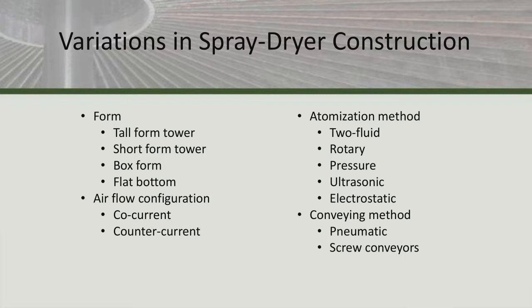There's various methods of atomizing the liquid, the most popular one being the rotary atomizer. On the lab scale, you see a bunch of 2-fluid nozzles being used, but there's also high pressure ultrasonic nozzles, electrostatic nozzles, and actually this slide doesn't show it, but there's another one called pulse combustion atomization that was invented here in the US.